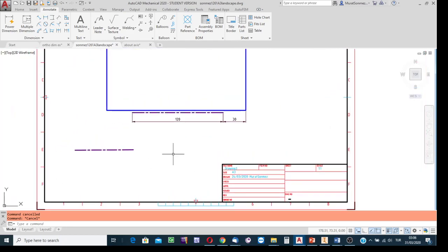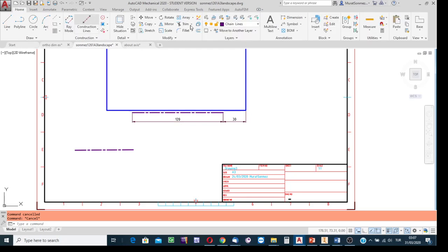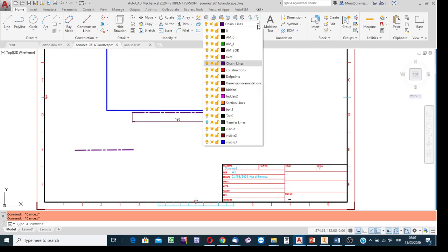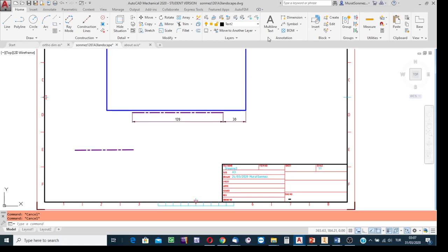What is the requirement? Write the requirement in technical format. How? In AutoCAD, using the text facility along the home ribbon, find the text facility, drop the list and select multi-line text. Before doing this, first drop the list of the names of the layers and from the list select the text layer. Already decided to keep technical notes in one of the layers, I selected the text layer and then start the text typing process. Click on this listing arrow and select the multi-line text option.